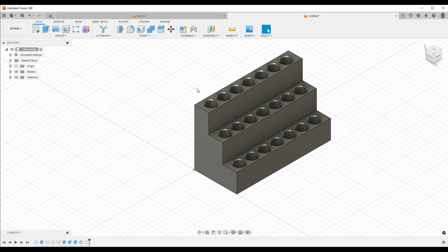In this lesson you learned two interesting options that can make it easier to create 3D models in Fusion 360. The first is to copy the sketch from plane to plane, and in this case we had a simple sketch of the circle, but there are often situations in which this sketch is more complex and we have to create such a sketch on one plane and then on the other plane. And copying sketches can save time. And the second thing is a rectangular pattern, which allows you to make any number of copies of the selected feature in a linear pattern. This in some cases can speed up and make 3D modeling in 3D CAD systems easier.